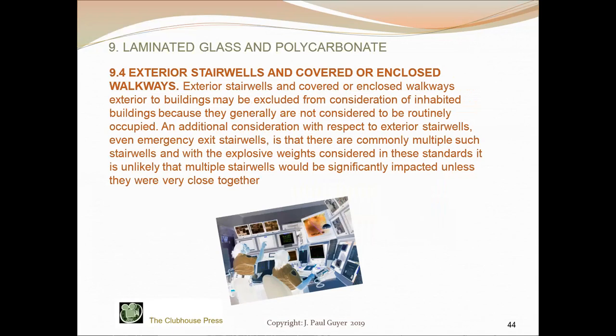An additional consideration with respect to exterior stairwells, even emergency exit stairwells, is that there are commonly multiple such stairwells, and with the explosive weights considered in these standards, it's unlikely that multiple stairwells would be significantly impacted unless they were very close together.